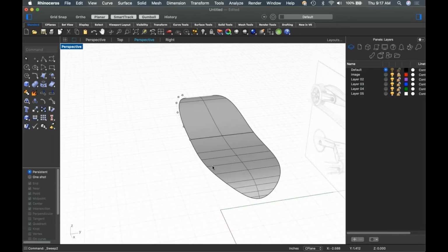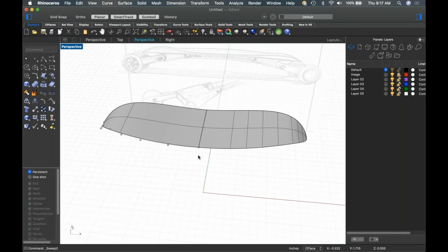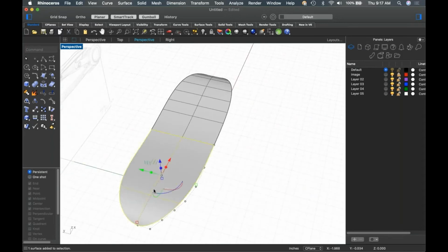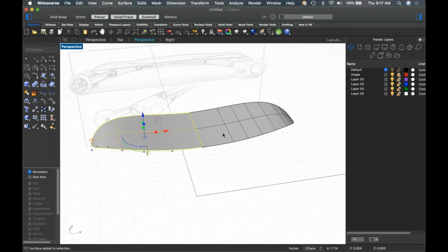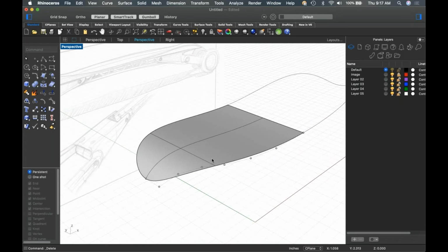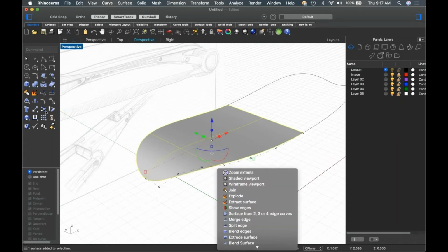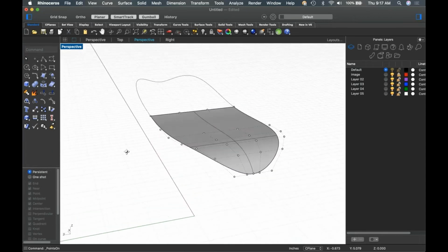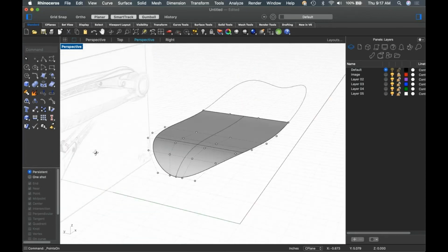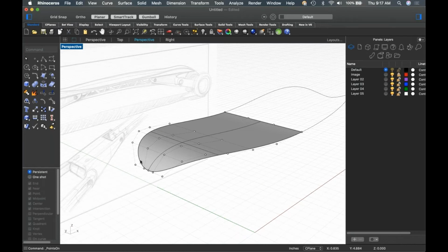And this is not terrible. Like, don't jump off a bridge if your surfaces look like this, by all means. But if you can make surfaces that look like this, which only have one isoparam, this is called a single span surface. That's kind of our goal, right? That's kind of what we're looking for. And the cool thing about this is, because this is a single span surface, that means that the points on the surface are really well organized and really nice and really easy to get to, which makes this, say it with me, class, easy to edit.